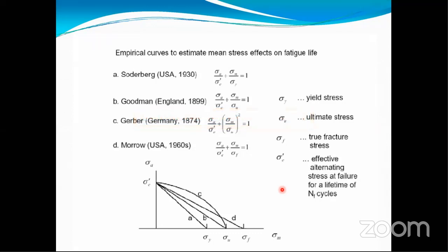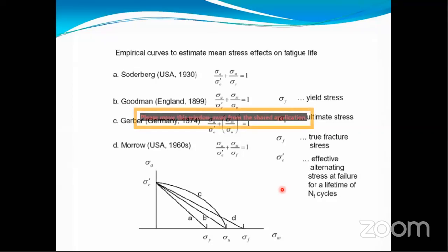But in actual practice, mean stress is certainly not equal to zero. So we need to account for this effect while estimating the fatigue life.